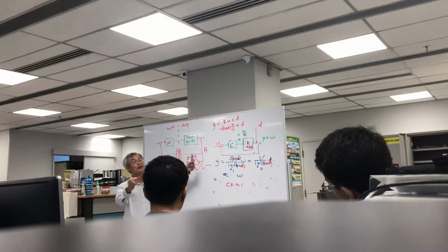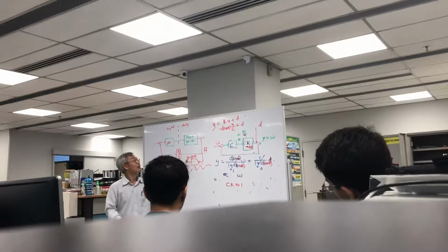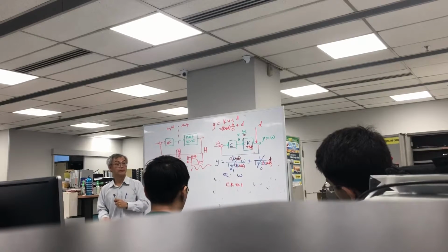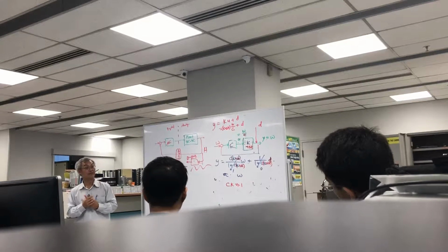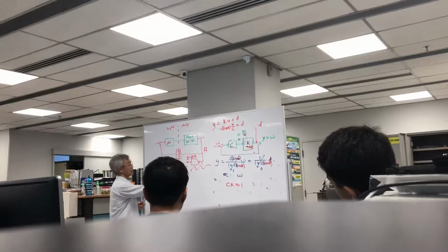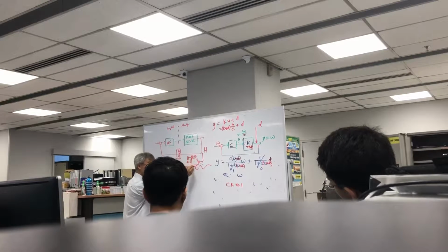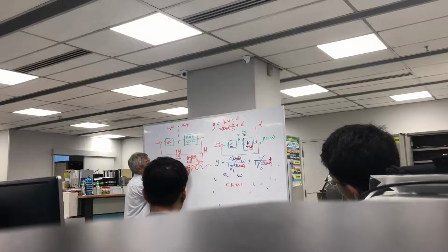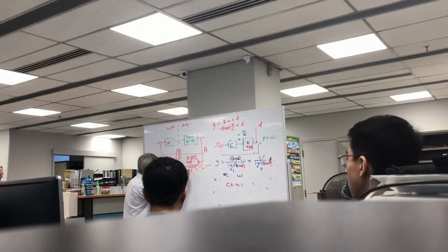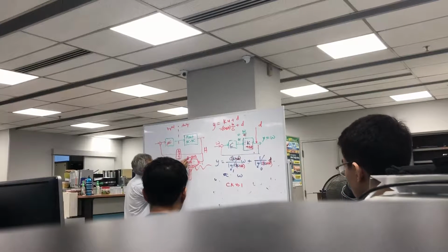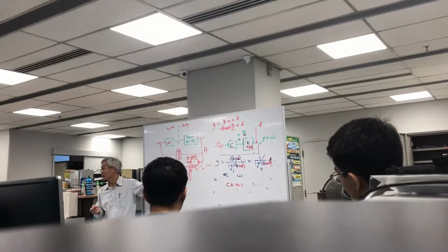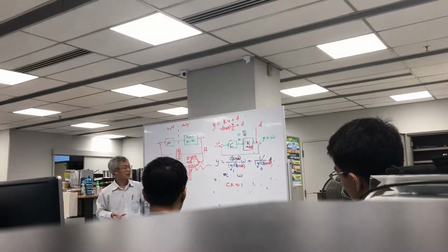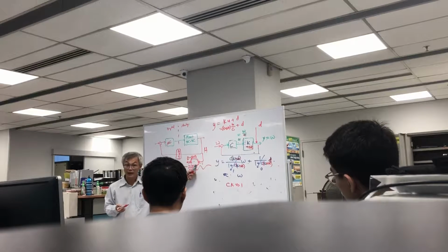I suppose 0 corresponds to 0% humidity, 1023 corresponds to 100% humidity. How do you bring this number into here? Digital input. Okay? So it depends on what you have. Either I2C, or digital input, if this is 10 bit, and then you do the interfaces and so on.